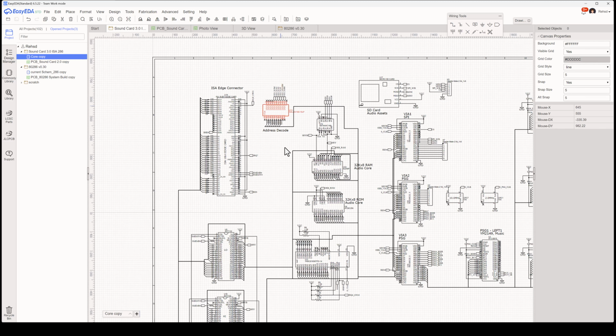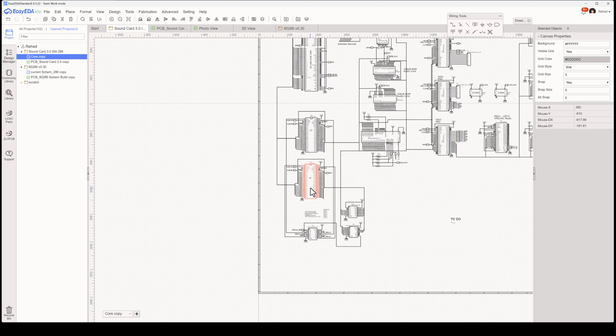And as a reminder, the purpose of that dual port static RAM is that from my 286, I can write commands in a queue in that RAM. For example, say play song 1, play song 3, that type of thing. I can trigger the interrupt, and then the sound card will go read from that queue essentially, and then go ahead and process that command and then clear it out, and just have a loop-around type of queue system.